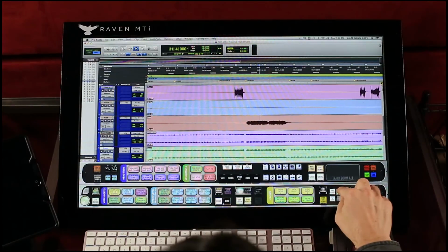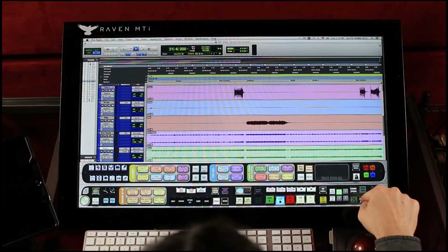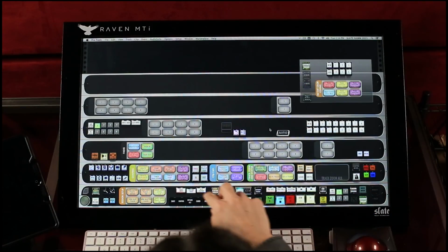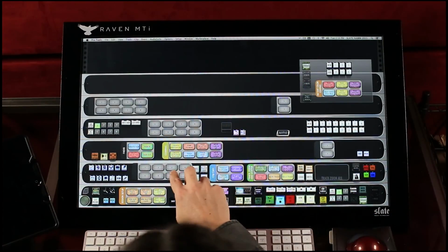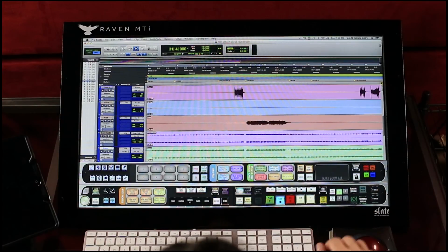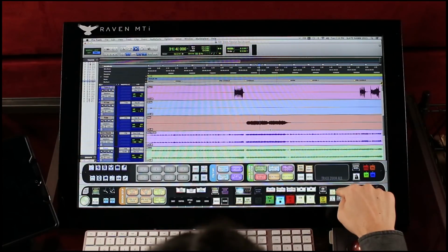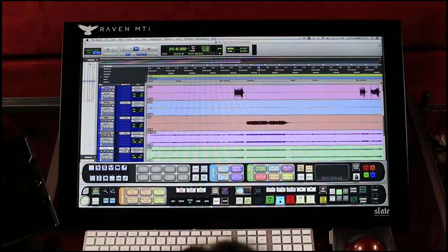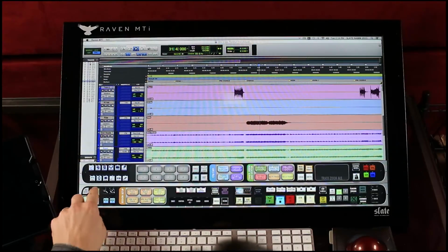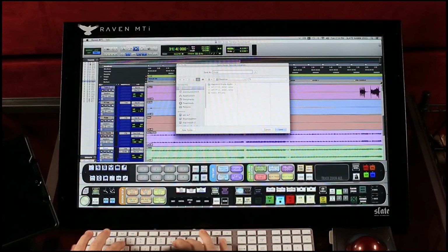When making changes to layouts, it is important to save your layout changes separate from the full Raven session. After changes have been made to a toolbar on a layout, hit Save Layout and then overwrite the current one by touching the highlighted layout. You'll see the Save Layout light turn off as a confirmation of its saving. Once your layout is saved, you can save your Raven session.